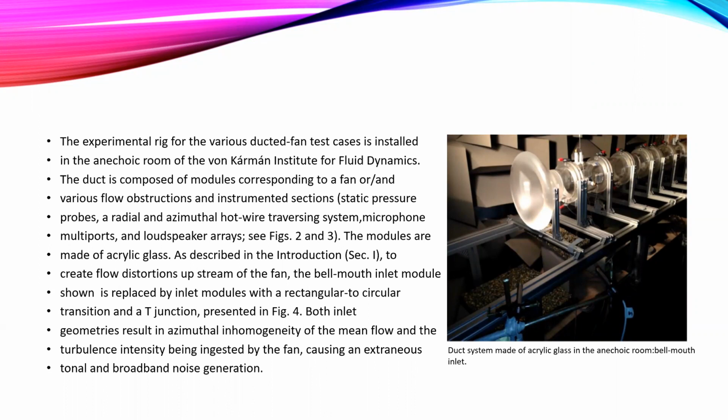Static pressure probes, a radial and azimuthal hardware traversing system, microphone multiports, and loudspeaker arrays. The modules are made of acrylic glass as described in the introduction to create flow distortion upstream of the fan. The bell mouth inlet module shown is replaced by inlet modules with rectangular to circular transition and a T-junction.